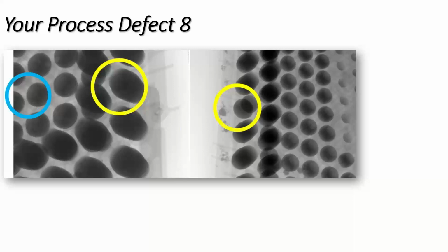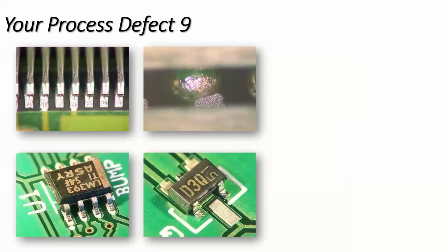I prefer dip paste because it overcomes issues of open interconnections, because you're putting something which is a solder adding to the joint. If you've just got 2 balls, and if there is any small gap between those 2 balls, the flux won't aid the connection, because you're not adding any more volume of solder to those 2 connections. You're just adding flux, which is providing the opportunity to solder, but not actually giving you any more volume of solder, whereas dip paste adds solder volume to the potential connection.